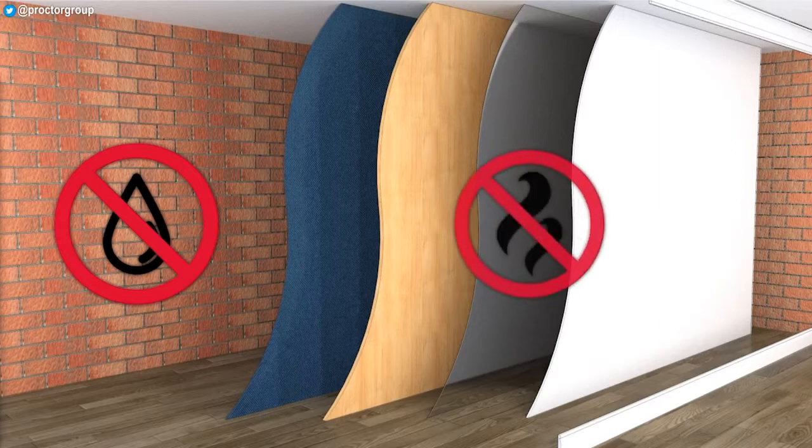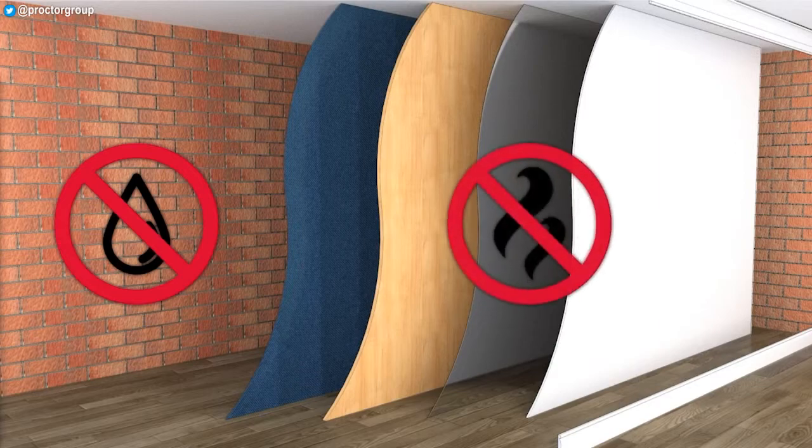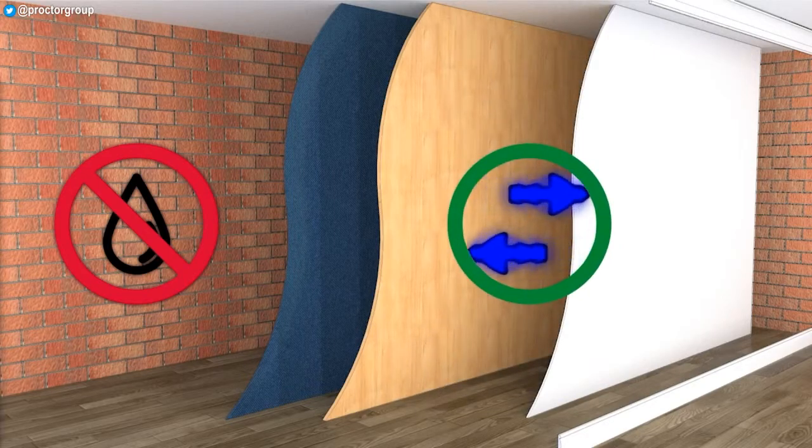Both the wallboard and Direct Fix panels are supplied with an inbuilt foil layer for vapour control. However, if the design criteria requires higher permeability, this can be omitted on request, giving a more breathable wall construction and allowing the free passage of moisture.